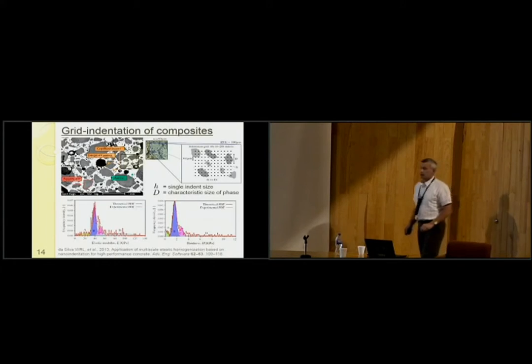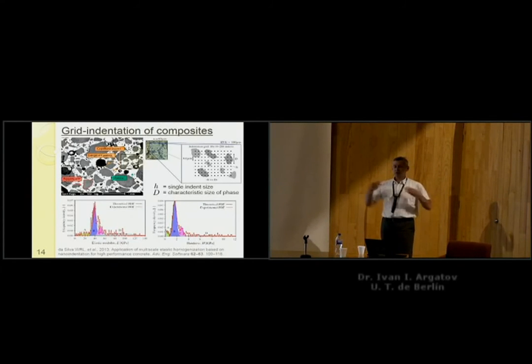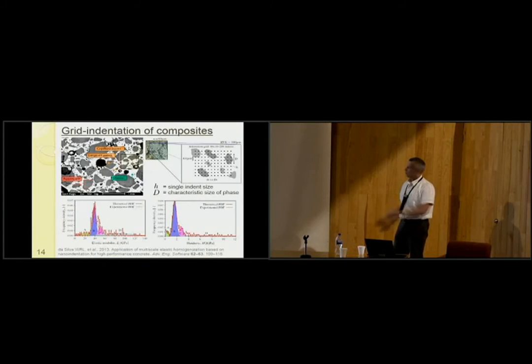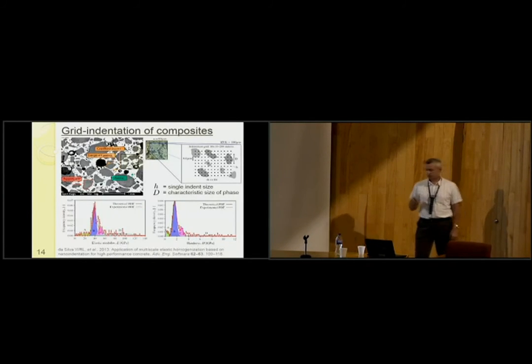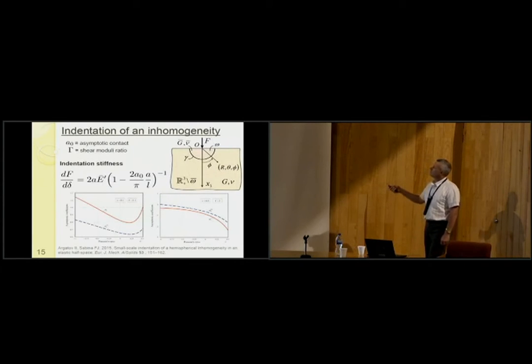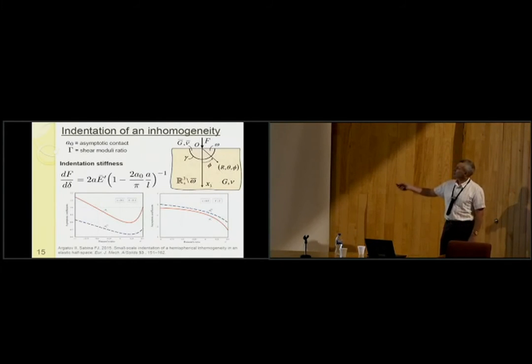So we formulate the inverse problem of calculating properties of the individual phases based on indentation. And a very important contribution to this problem was given in our joint work with Professor Sabina, published this year, and it is based on solution of small-scale indentation of a spherical inhomogeneity in elastic substrate.